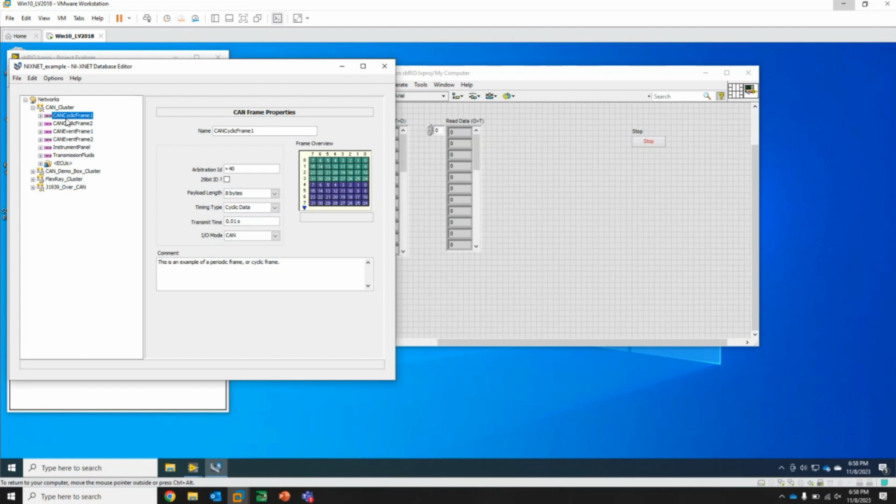So what I found is I can go in there and I can change the name to whatever I want. I mean, the OEM has only said, this is the arbitration ID that I'm using, and here's how the data is packed. So I could say, well, I'm going to call that wheel speed. And now within the programming environment, I've used a property node to say what ID is my wheel speed. And when I receive a message from that ID, now I can just pop wheel speed up. And if the OEM changes what arbitration ID it is, I just get a new CAN database and I just rename it, and that name is available. So there's a lot of stuff you can do with this to prevent yourself from having to constantly rewrite or update code to support those types of changes.